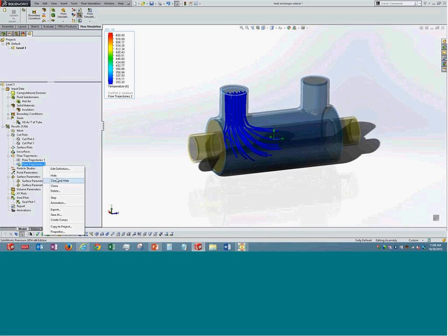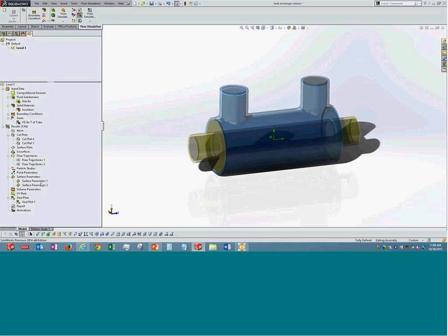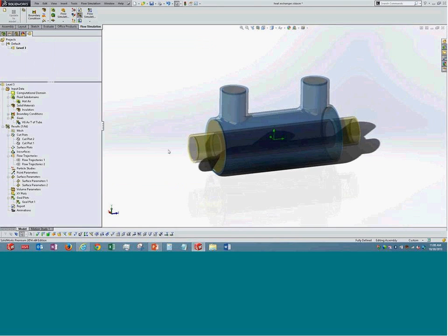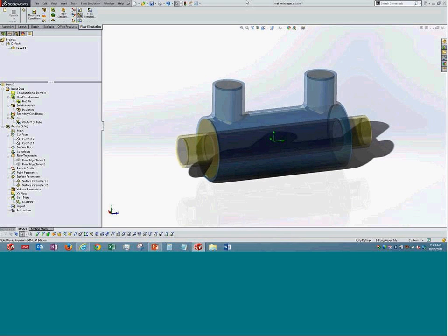One of the questions is, can the software calculate the overall heat transfer coefficient for this case? There is an automatic option, but with the goal feature that I showed you, we can specify an equation goal for any kind of output. We need to specify those details over here. You can see this is a very easy interactive calculator. We can directly take the inputs from the front end and calculate the heat transfer coefficient.